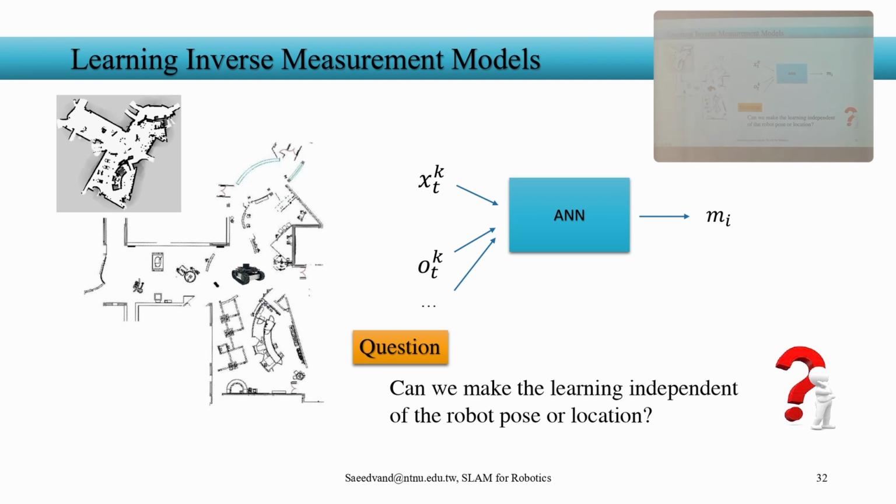Can you expand that a bit? This one? Yeah, here at the first stage, let's say the robot has these poses as input. So one input says where the robot is exactly. If we know where the robot is, it means that when the robot moves in the environment, it can update all grid cells. Don't consider these circles. Since I know where the robot is, I can say that this obstacle is over here, because I know the coordinate here.